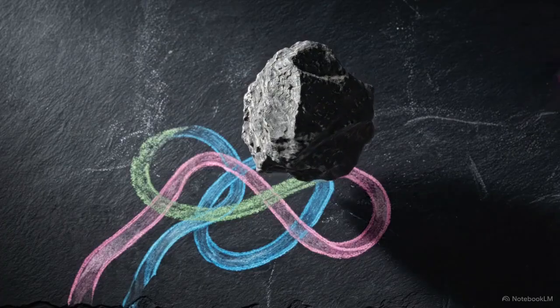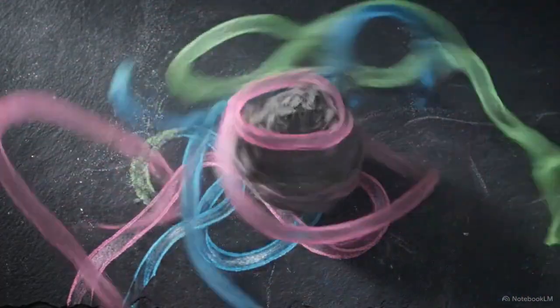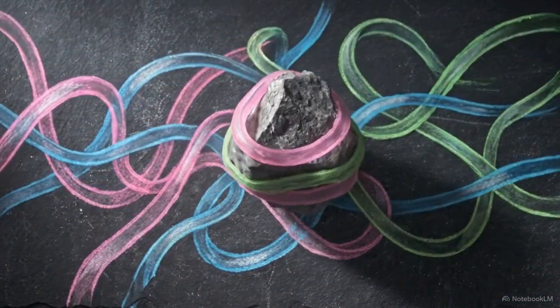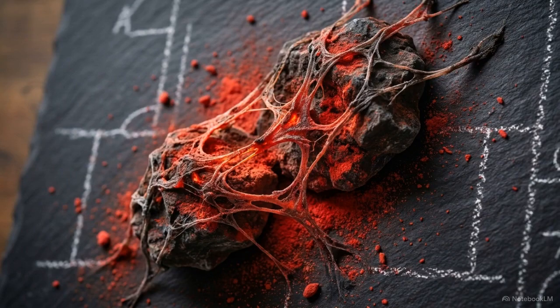This internal ionic fixation is reinforced by an external physical barrier. Long synthetic chains of PHPA polymers are added to the fluid. Through encapsulation, these polymers wrap around the drill cuttings and the wellbore wall, preventing any remaining free water from entering the clay structure. But standard polymers degrade as temperatures rise.